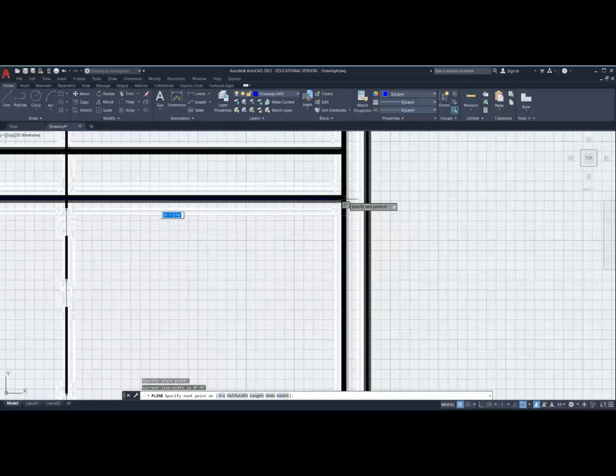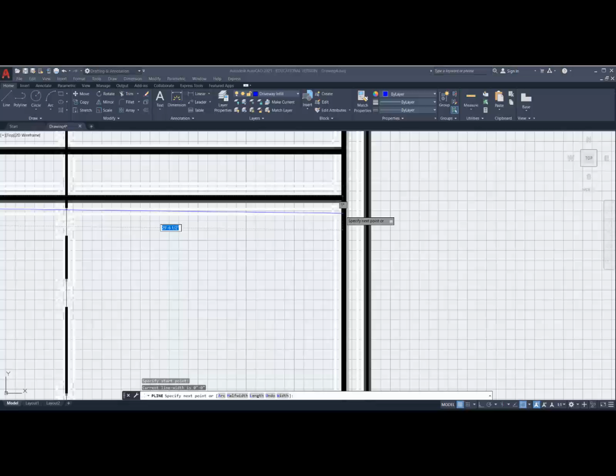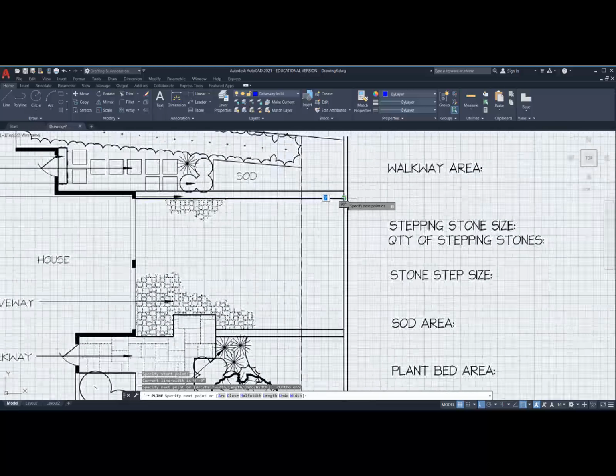And you'll notice that my line work, when I scaled it up, was pretty well dead bang on in terms of rotation. So I'm going to change here to F8 to give myself a nice horizontal and vertical line. And you can see there's a slight rotation change here. That's okay. I'm going to click on that point there and move downwards.